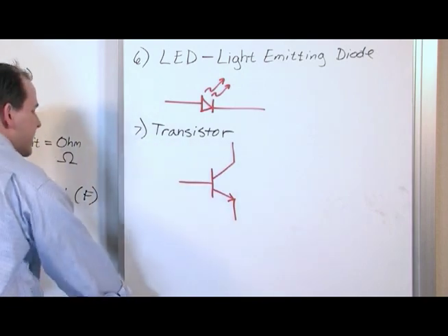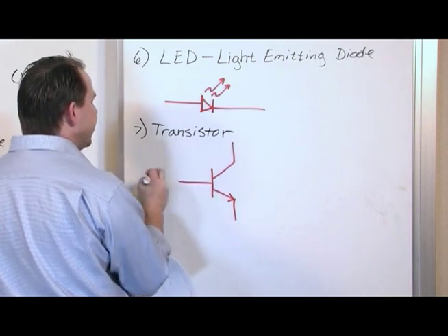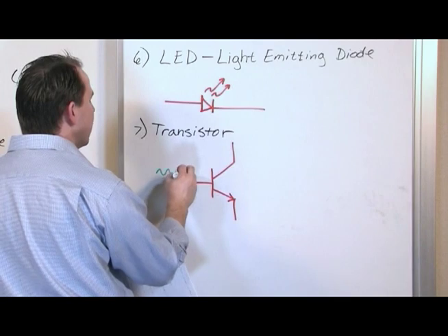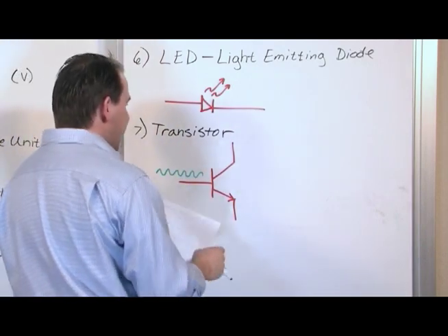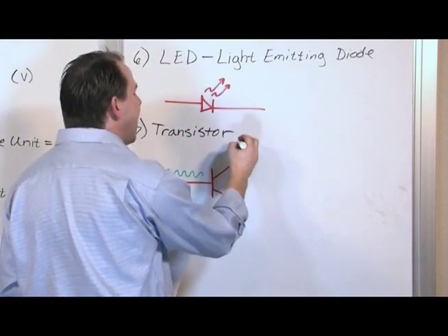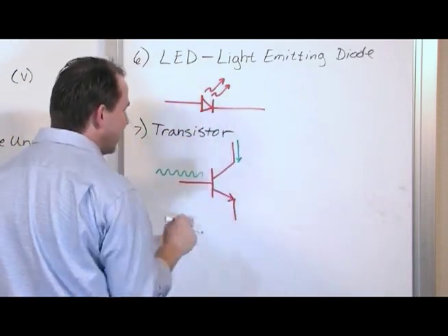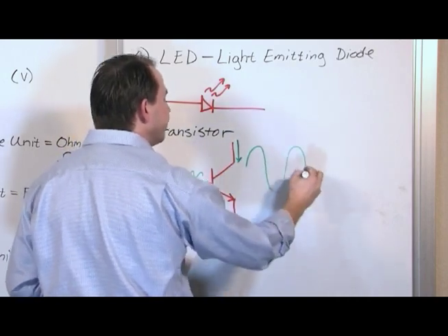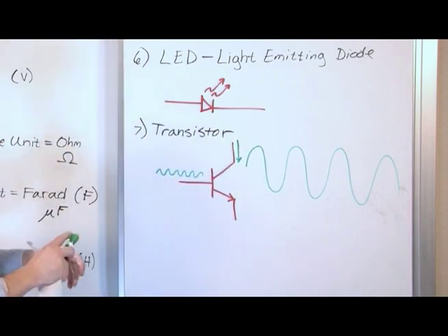All right. Now, I'm not going to get into transistor theory here, but basically what I was saying a minute ago, if you're sending your voice in over a wire, let's say, you may have a very small voltage signal coming in on that wire, right? The input comes into this leg right here. The output has current flowing down through the thing like this. If you stick a voltmeter here, you might see something that looks like this, much larger. But it's a direct replica of the input, and that's how it behaves as an amplifier.